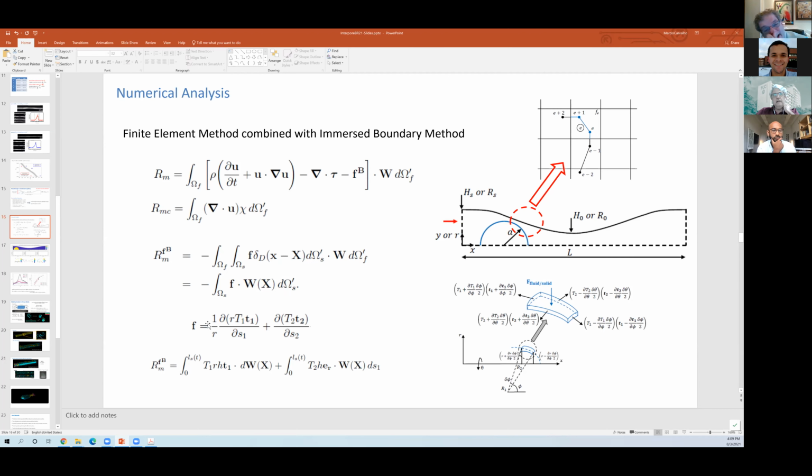Okay, I got it. I thought it was some sort of boundary condition, but no, you treat the sphere as something which is interacting with the free flow at all points. Yeah. So the point is that I'm using a simple elastic model that is just like a shell equation. So it's a one-dimensional model where there is a tension along the shell. So the surface divergence of this tension is the net force that's acting on the shell. And then for it to be in equilibrium, that force comes from the fluid.